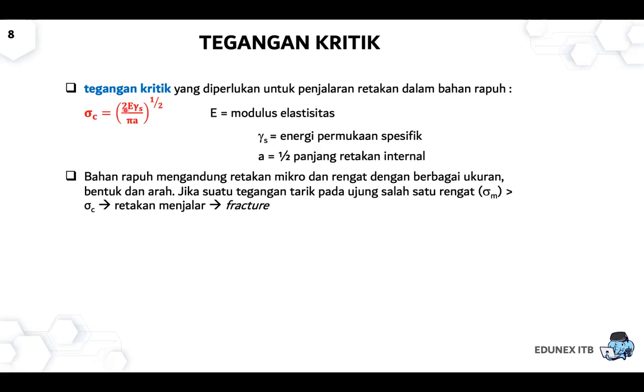This is the critical stress used to propagate the crack. It is 2 multiplied by the modulus of elasticity multiplied by the surface energy, divided by pi, 3.14, multiplied by a. So that is the critical fracture stress.